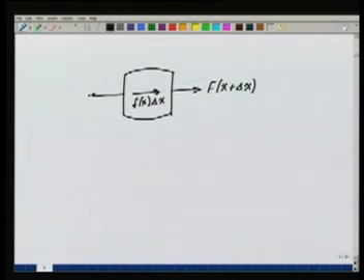Here is the axial force F at x. Since we have put the spring on both sides, we will only get an axial force effect of the spring, which will be opposite to the motion, given as (k0 plus k1 u squared) into u delta x, because the spring constant is given per unit length. So that is into the length delta x into the displacement of this part.